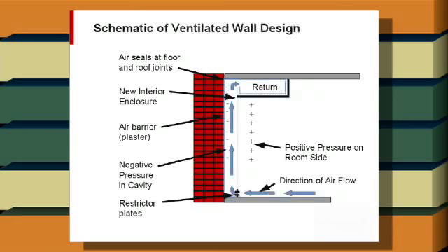You have negative pressure behind here, which building envelope folks like, because you're not pushing humidified air into the building envelope. And the conditions are the same on the front and the back of the wall. Now, all this, of course, is predicated on the notion that even without all this, right, the wall still must have sufficient R value to not condense under those conditions.